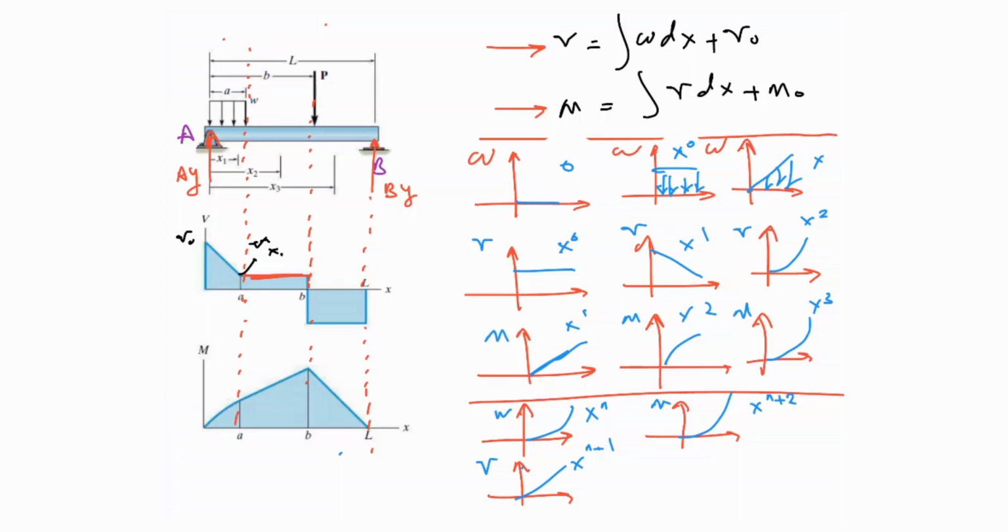Today I'm trying to show you how to use the concepts of the previous video to plot the shear force and the bending moment for the beams. If you remember from the previous video, what we have done was using some formulas to develop some plots, and we said that we may have different distribution of the load. That could be a single force like this one, or a distributed force like this one, and based on that we would have different manners on the plot of shear force and bending moment.